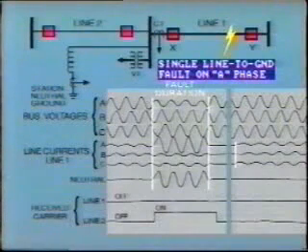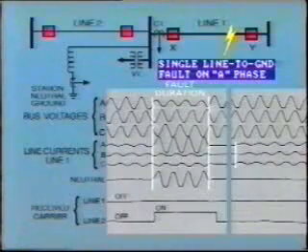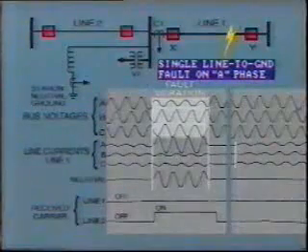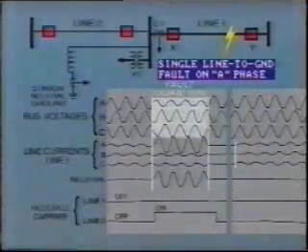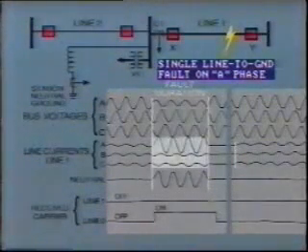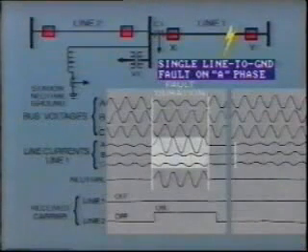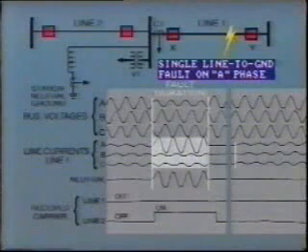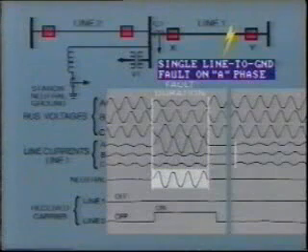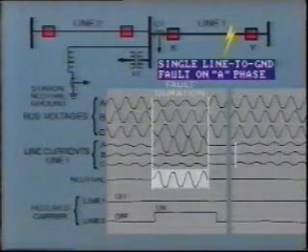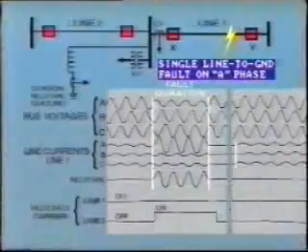Number 1, the fault was a single line-to-ground fault on the A phase of line 1. We know this from the depressed A phase voltage at the substation bus. The other bus voltages are normal. Also, the A phase line current undergoes a sharp rise, while the other phase currents are unaffected. Finally, the station neutral current also increases from almost nothing to a large value. This indicates a line-to-ground fault.